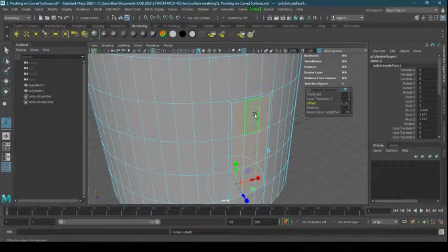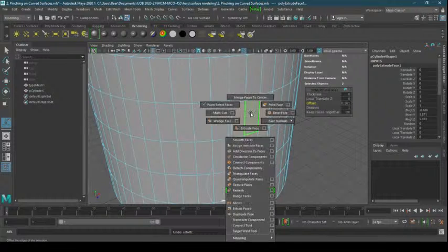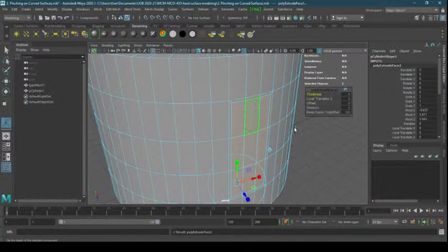Once I apply the offset, I will press Shift key again, right click again, extrude again, so it will apply a fresh extrude. Now I will go to thickness and apply thickness inwards in the negative value, so it will go inside.